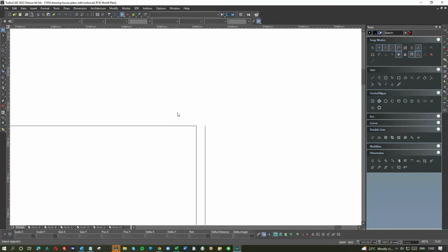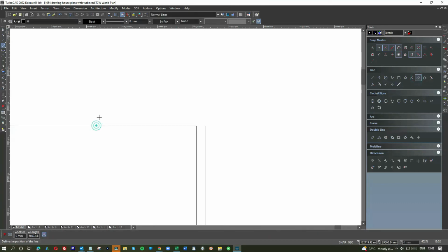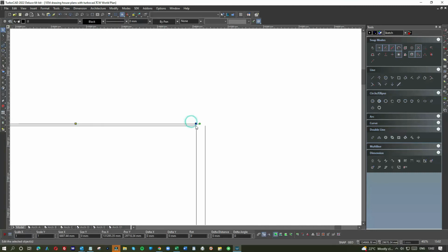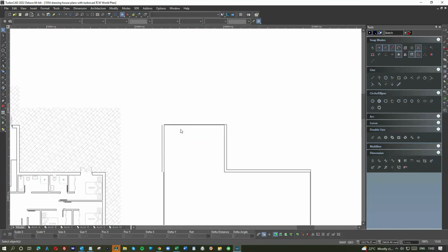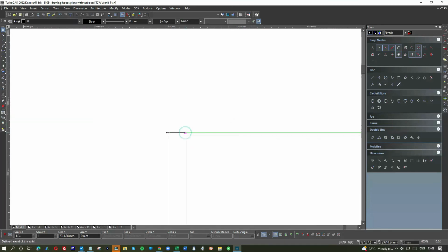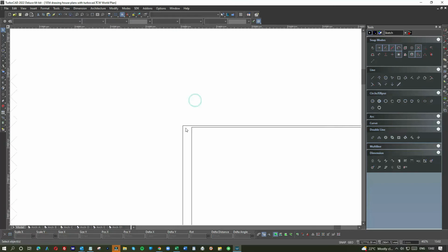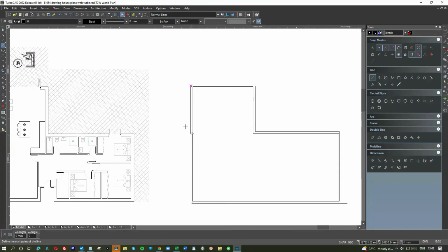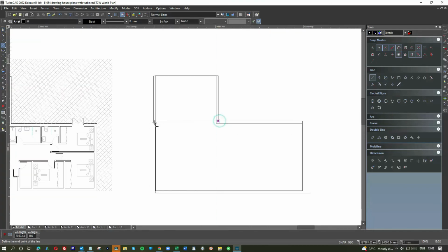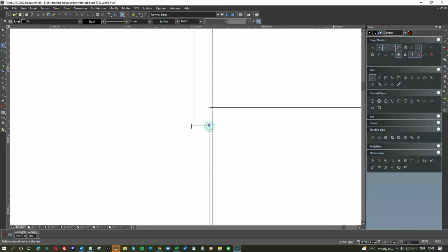This is the outline, and likewise the apex is going to be about 50 mil further out than the wall, tab 50. As a young designer, it's easy to forget that the roof is a little bit bigger than the actual building, and some people will do the roof exactly the same size, which of course it's not. You have to allow for the other bits and pieces.